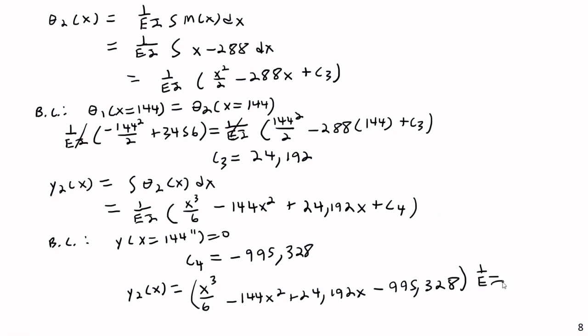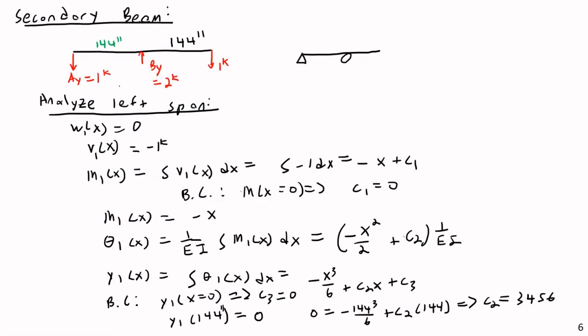So why am I working through all this? Well, if you remember back to the idea of the force method, what I am trying to do is find this deflection here. I want to know the deflection, basically this here. This would be my lowercase delta cc.